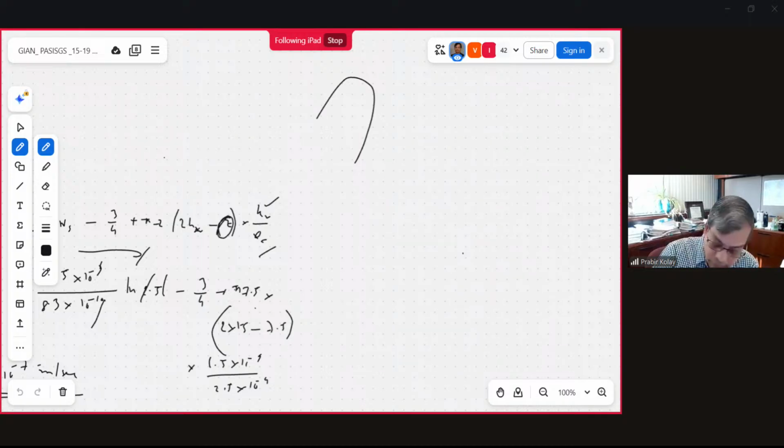Now, if everything is given, KV1 is 3 times the vertical KV2, and that's why it is mentioned in the problem: the vertical permeability is improved 3 times. So we have 3 times KV2 times KV2, divided by 3 times KV2 minus KV2.